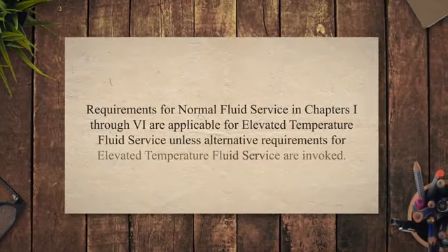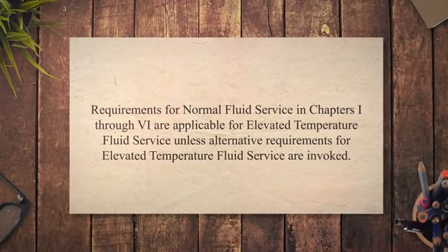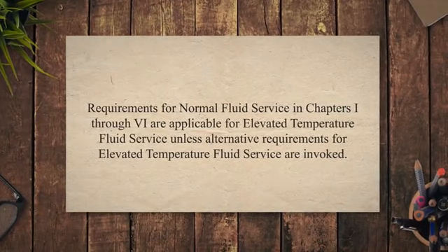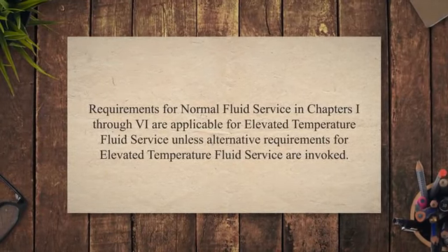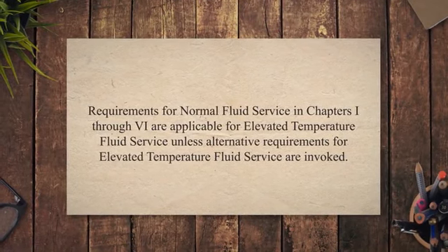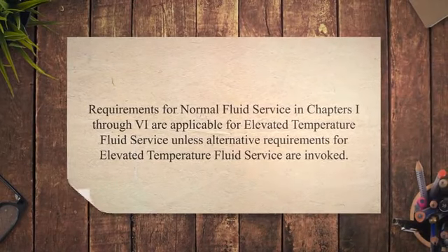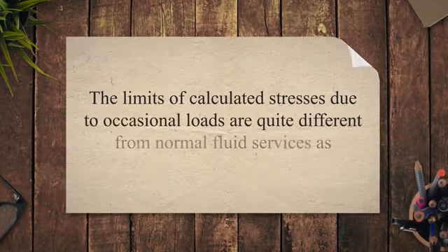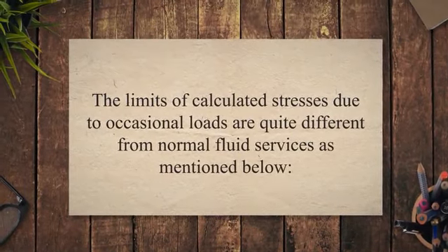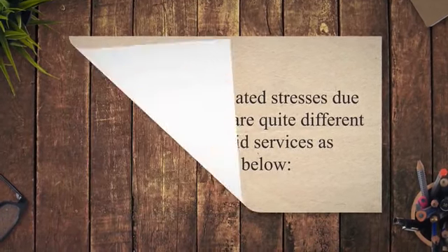Elevated temperature fluid service applies when the piping metal temperature is sustained at or above TCR. Requirements for normal fluid service in Chapters 1 through 6 are applicable for elevated temperature fluid service unless alternative requirements for elevated temperature fluid service are invoked. The limits of calculated stresses due to occasional loads are quite different from normal fluid services, as mentioned below.